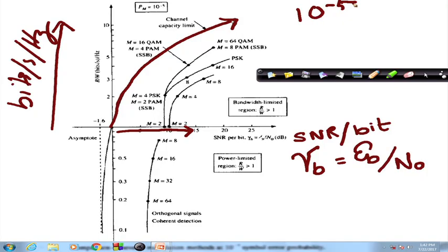Of course, just a side note, for other situations like wireless links and short links, especially mobile communication links, these uncoded performance numbers can be taken to be 10 to the power of minus 3 as a benchmark, but generally 10 to the power of minus 5 is a good reference point considering all kinds of communication systems. So, now going back to this particular curve, what we see here is the constellation, the point